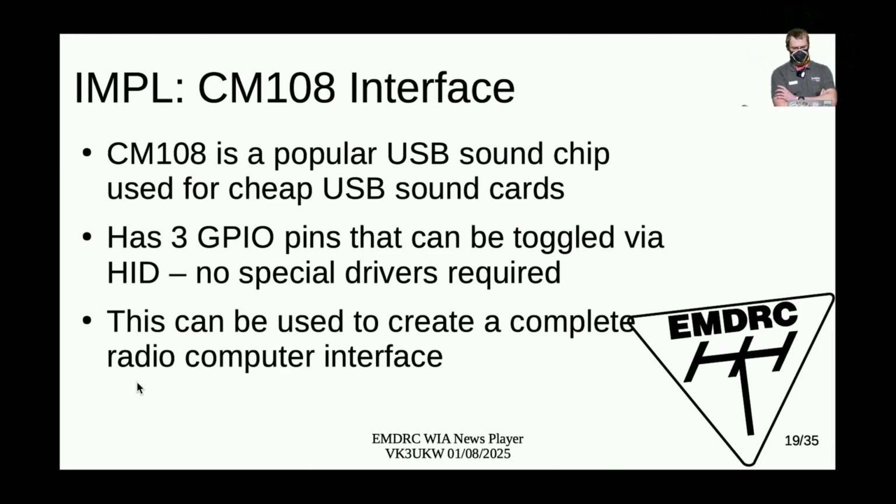And the great thing is that they have software control using the USB HID, that's Human Interface Device, protocol. That means you can interact with that without any special drivers. If you've got a USB sound card, and also GPIO pins that you can program yourself, then you have everything that you need to create a full radio computer interface to control transmission and audio or data into the radio and out of the radio.